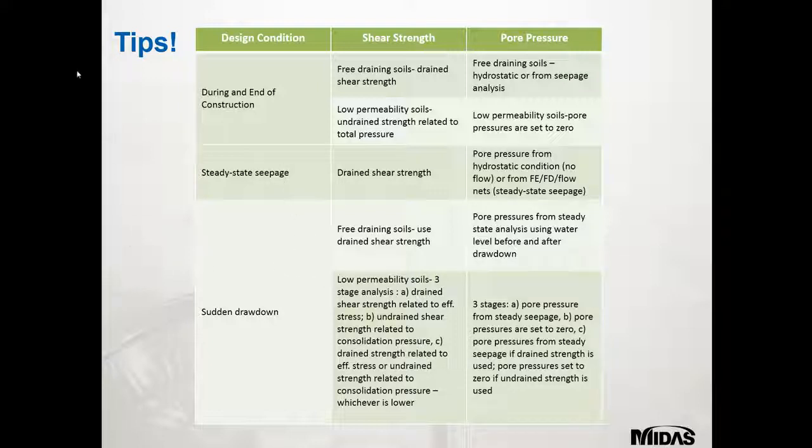Steady state seepage is in an embankment, be it high or low permeable soil. Under steady state, drained material strength is used. Pore pressures could be hydrostatic or derived from steady state seepage by FE or FD or flow nets.